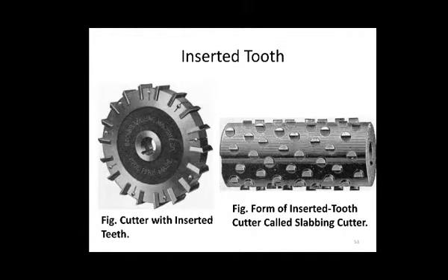These blades are renewable, the cast iron body being used many times. Another form of inserted tooth cutter consists of round hardened steel pins driven into holes in a cast iron body. This cutter is also permanent in form. So, as you can see in the figure, broken teeth cannot be replaced, and when the teeth are worn almost down to the body, the whole cutter is thrown away.